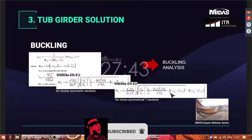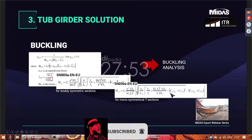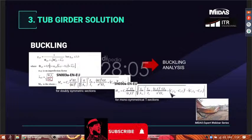The buckling resistance of the steel members depends on its slenderness, that is a function of the critical elastic moment. European codes provide some closed form solutions for this. We can see them here. But they all refer to double symmetrical sections and monosymmetrical T-sections. For our tub girder, the only way to calculate the M-critic value is through a buckling analysis, and for this MIDAS can help.